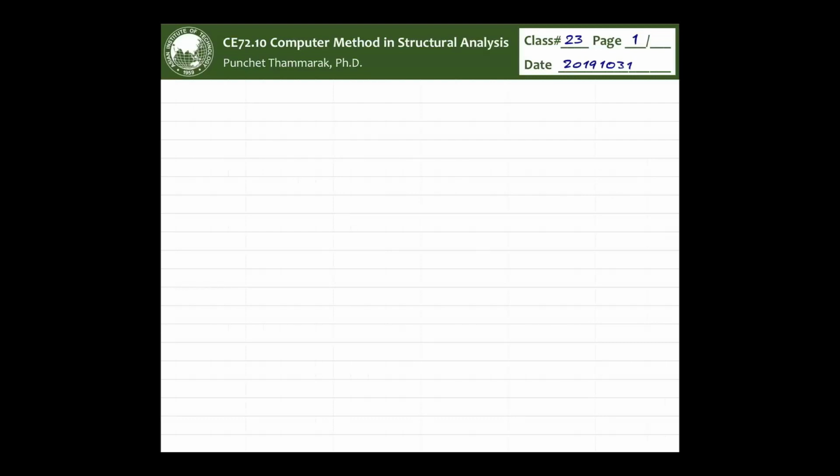Last time we used the geometric stiffness matrix. I showed you how to use it to determine the buckling load. That's the Eigen buckling or bifurcation problem, where you can find just one root of the solution, though it's not necessary to be just one. But basically, the buckling load will be controlled by the first Eigen value, which is the lowest, because as you load up, you meet the lowest one, and then your system just fails.